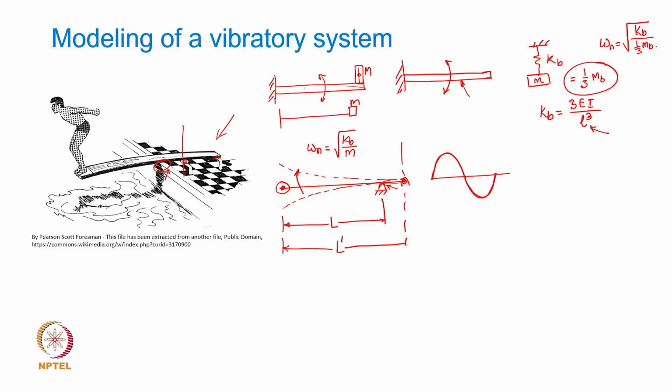Okay. Then the system is not really a linear vibratory system, it is going to be a bilinear vibratory system. In one half of the oscillation cycle the stiffness is different, and in the other half the stiffness is different. But why are they bilinear? Because in one cycle there are only 2 possible values of the stiffness.